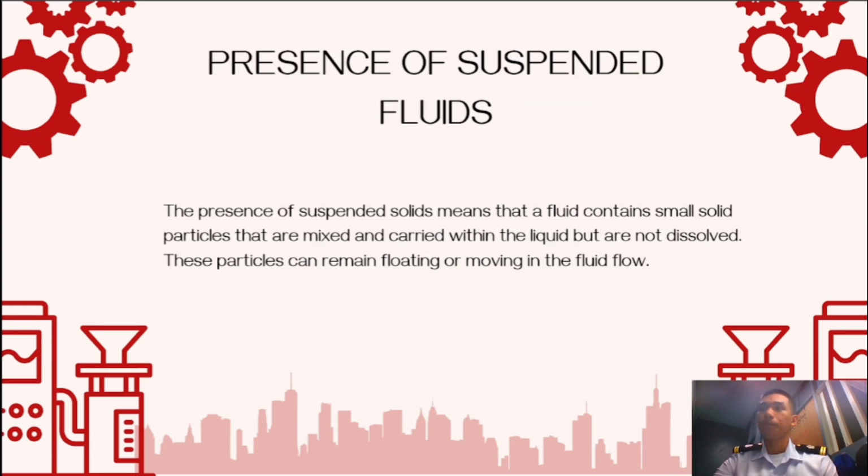So next is the presence of suspended solids. The presence of suspended solids means that a fluid contains small solid particles that are mixed and carried within the liquid but are not dissolved. These particles can remain floating or moving in the fluid flow. So it defines the fluid as containing undissolved solid particles carried in the stream. These floating or moving particulates introduce mechanical abrasion and physical blockage throughout the process loop.